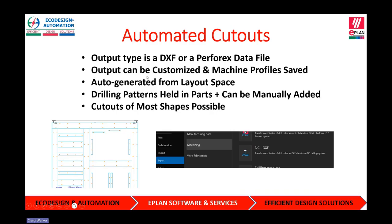The outputs can be customized in terms of how you want your coloring done: what color do you want tapped holes, what color do you want drill holes, do you want text marked on it, do you not want text? So this can be completely customized, and you can have a machine profile saved. And we actually work with CSL and their Perforex machine, and we have a saved profile, and this profile can be saved, exported, and imported so that other people can use that machine straight away with a setup that we know works. We have the ability to auto-generate this from the layout space.